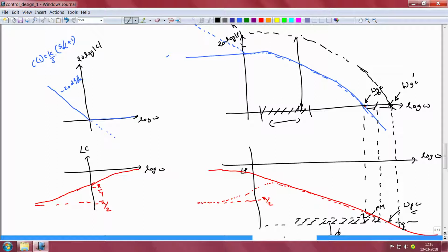Now with a PI controller there is nothing one can do. If one were to simply multiply the PI controller with this constant K1, then one has to accept an unstable system on one's hands. So how do we salvage the situation? Remember and note that we have managed to meet the performance specifications by making sure that the mid frequency gain is adequately high, but we are now paying price in terms of stability of the closed loop system.